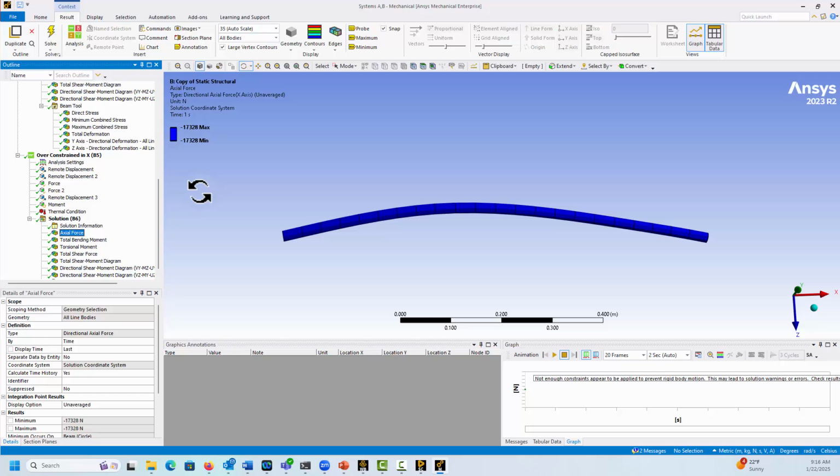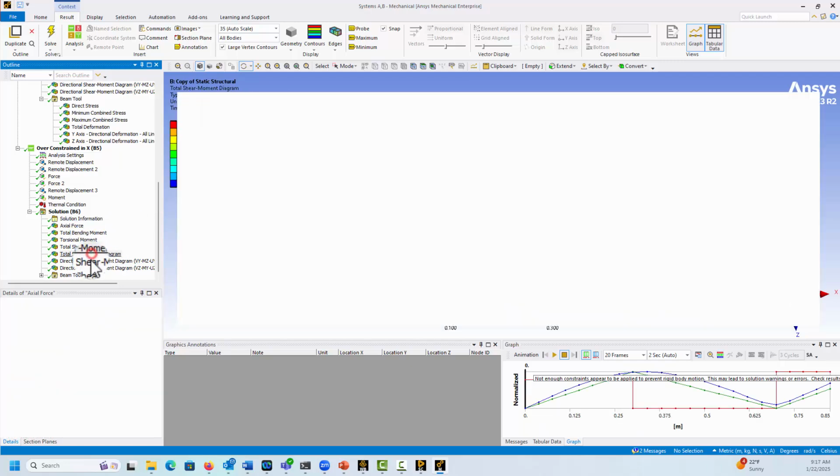A fairly modest change, right? 20 degrees C. That might happen in a hot working environment with things spinning, and 17,000 newtons of force were created. In practice, that might actually buckle the shaft. This analysis isn't going to account for that, but it could be quite substantial.